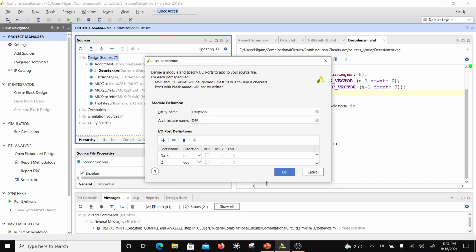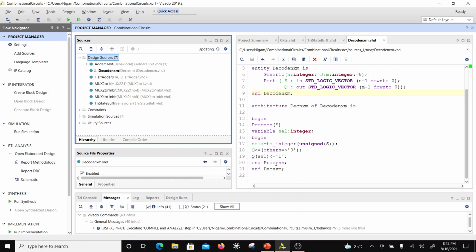Now here, when you talk about sequential circuits like flip-flops, you should be clear about the initial state. Either you have a circuit where you fix the initial state by set or reset, or you would have to code in the initial state.